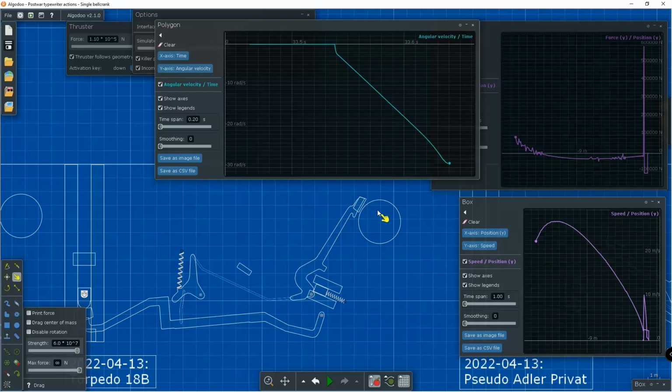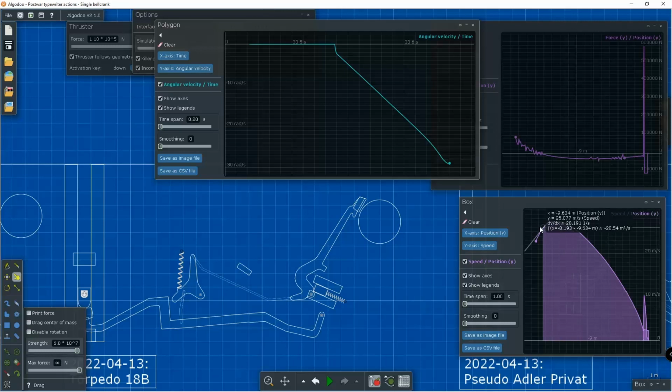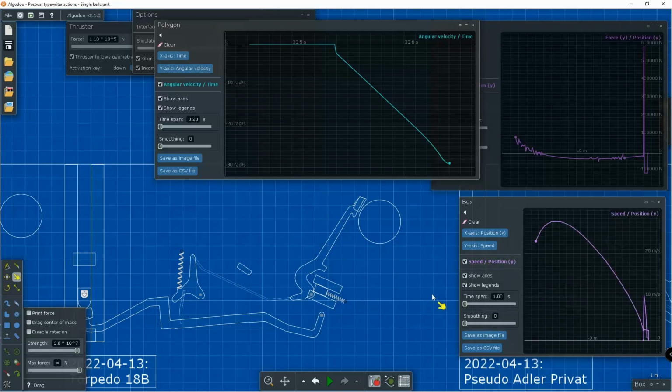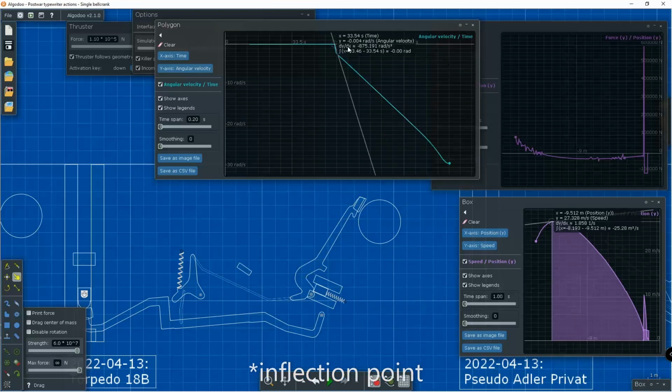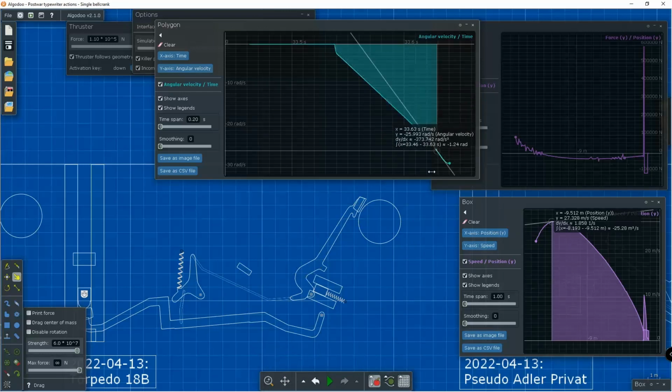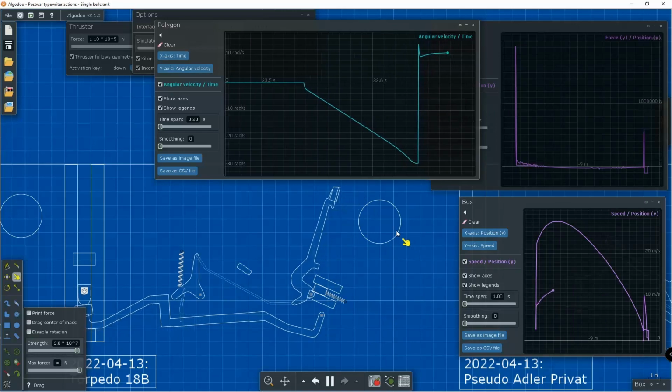and this is the case for most of the type actions that I've simulated, except for example, that Underwood type action, where instead of having a bowed speed curve, or speed with respect to displacement curve on your fingertip, we have that cusp here. That leads to a bit of unevenness or slight wavering in this rate. But now, given that this is basically the same, kinematically, across all these typewriters, then of greater interest is what happens after the release of the key.